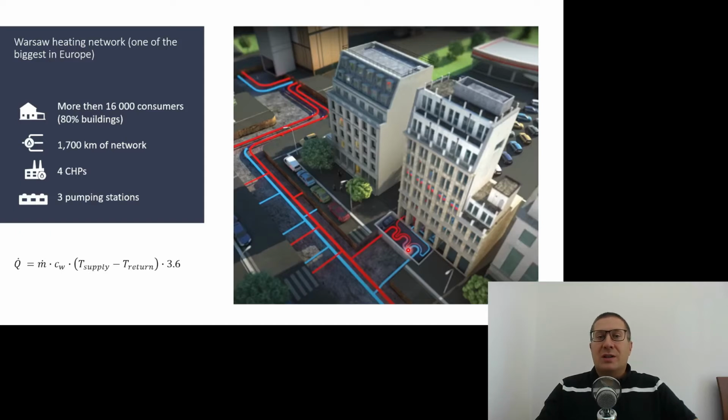So of course, on the other hand, we can say that we will just increase the temperature, keeping low flow, because we would like to save the cost of pushing the water, of using the pumps. But in this case, we will spend a lot of money on heating up the supply water, and moreover there are some losses in the network.